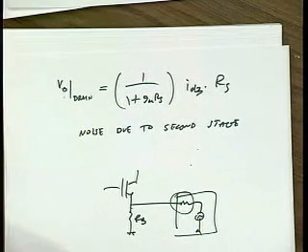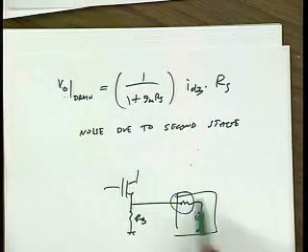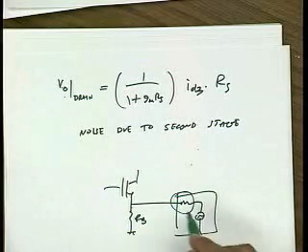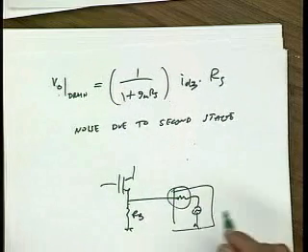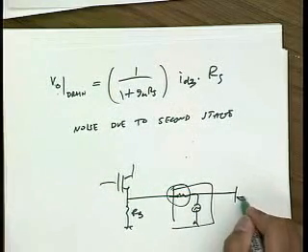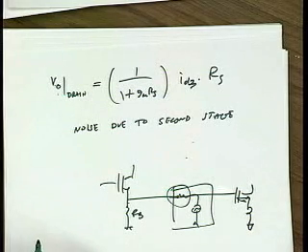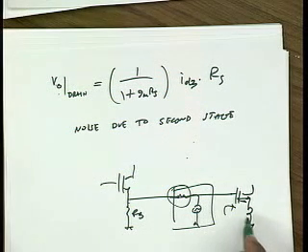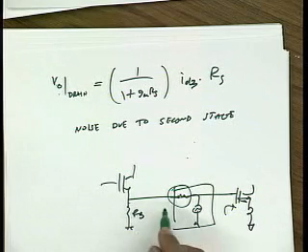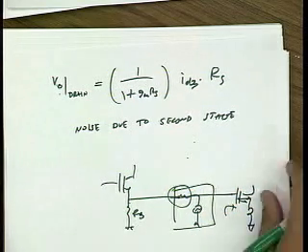we're not going to include the noise of this port in the noise figure calculation. Okay? Now, the reason is that this is going to drive another stage, and we don't necessarily know its impedance, and we don't know its equivalent noise. For instance, let's say the next stage is a degenerated device like that. Well, that device has a 50 ohm input impedance, let's say, but it doesn't generate noise. So it wouldn't be fair to include this noise, right? So that's one of the reasons for keeping it separately.